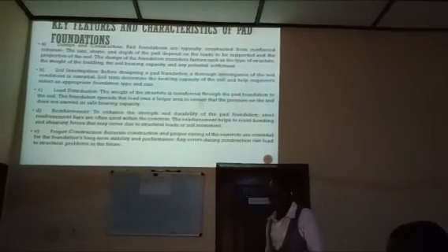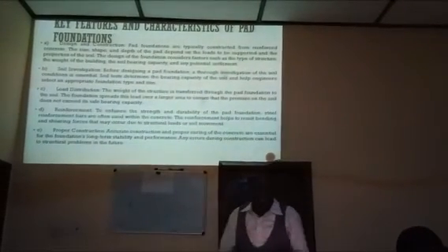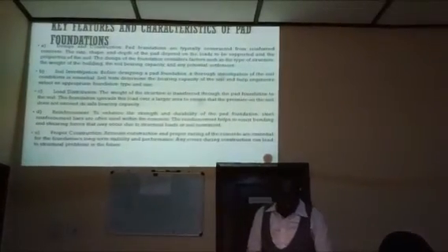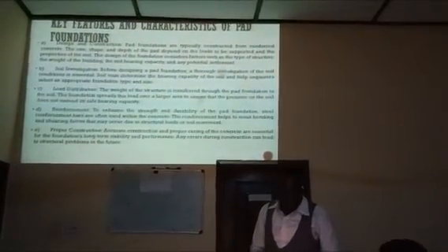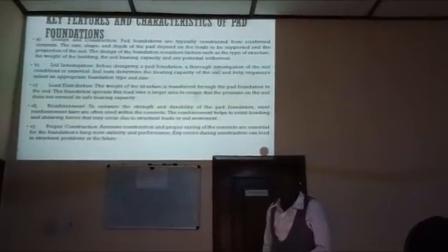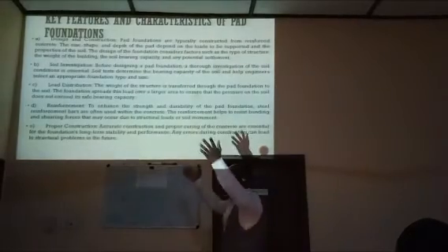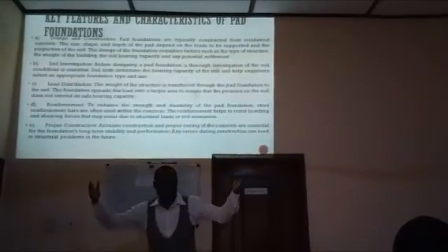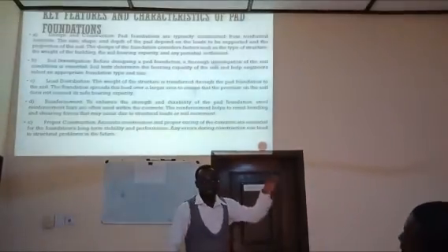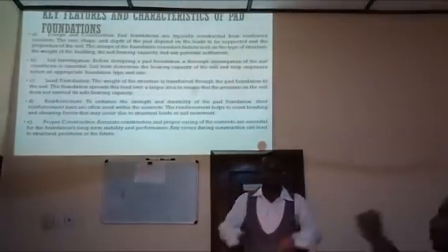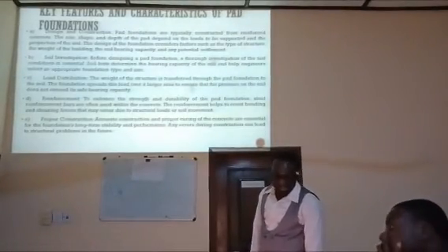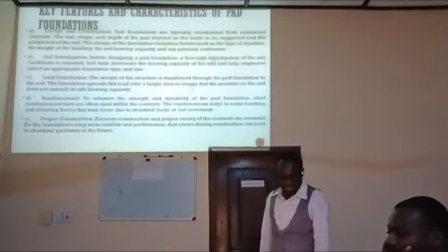Then the next thing is reinforcement. To enhance the strength and durability of the pad foundation, steel reinforcement bars are often used within the concrete. The reinforcement helps to resist bending and shearing forces that may occur due to structural load or soil movement. Then proper construction. Accurate construction and proper curing of the concrete are essential for the foundation's long-term stability and performance. So we need to cure the concrete and make sure we follow the normal mixtures and all that.